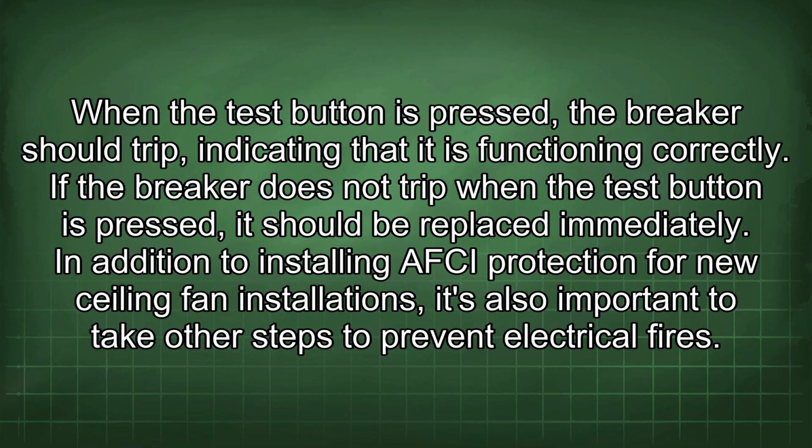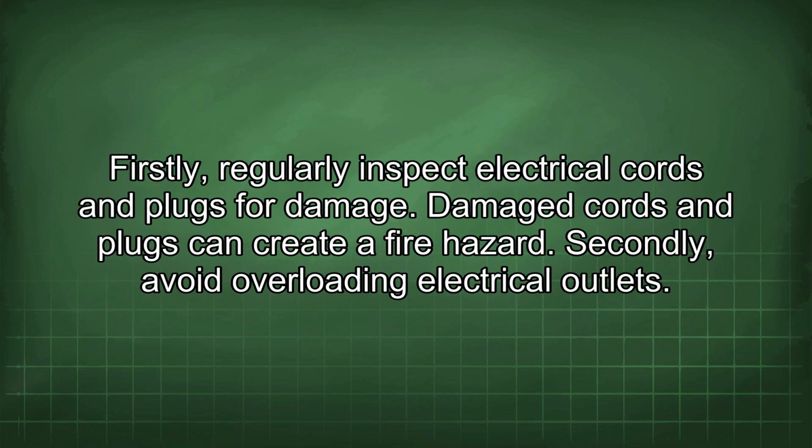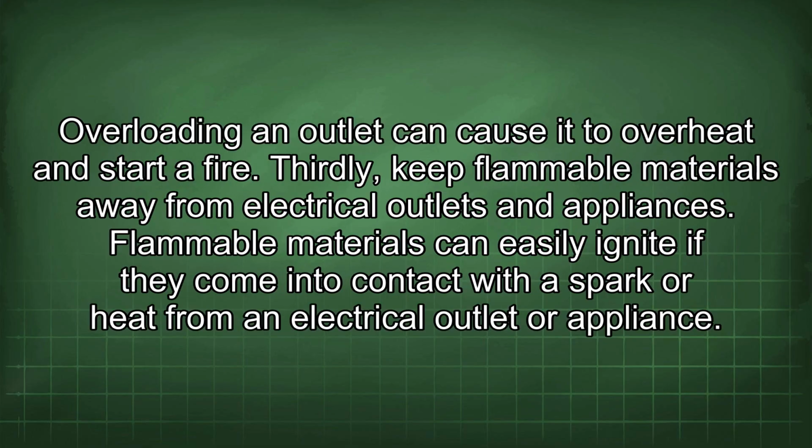In addition to installing AFCI protection for new ceiling fan installations, it's also important to take other steps to prevent electrical fires. Firstly, regularly inspect electrical cords and plugs for damage. Damaged cords and plugs can create a fire hazard. Secondly, avoid overloading electrical outlets. Overloading an outlet can cause it to overheat and start a fire. Thirdly, keep flammable materials away from electrical outlets and appliances.